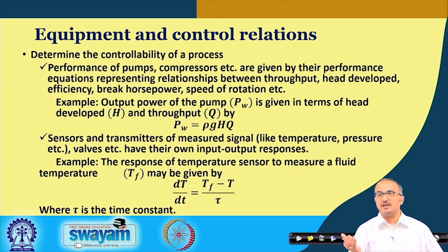Another example is the valve. Suppose you are having some flow rate through a valve. Depending on how much the valve is opened or closed, the fluid flow rate will change. Whenever you are changing the valve position, for example the tap in your day to day life, you find that the responses are not instantaneous. There will be a time lag, however small it may be.